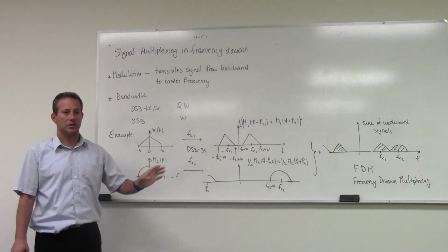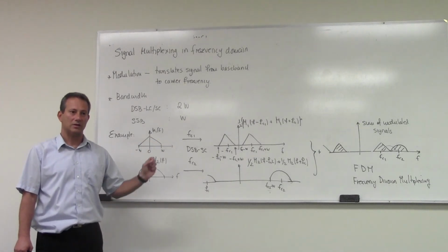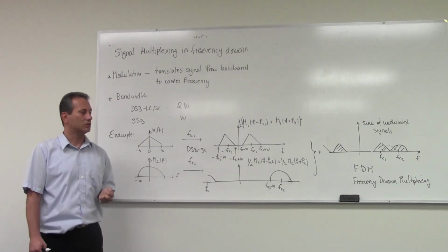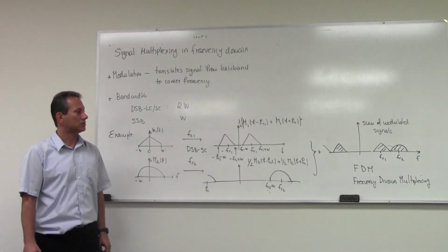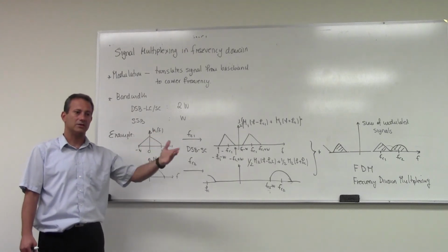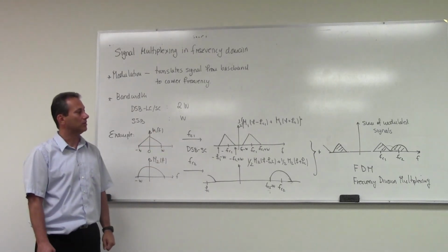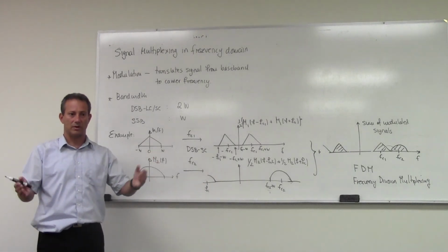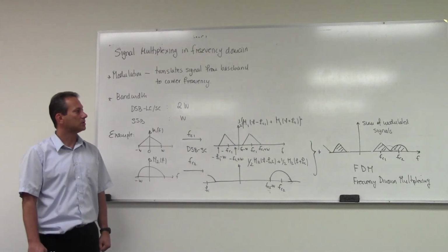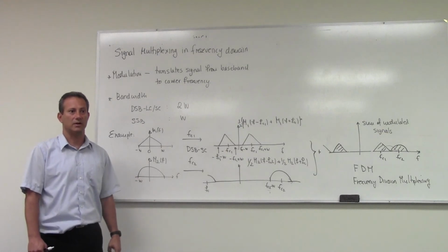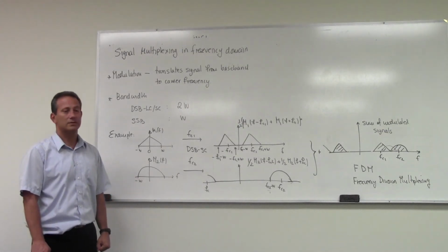Among all of these modulation schemes that you're going to cover, it turns out that single sideband is the most sensitive to the noise. So what that means is your signal-to-noise ratio needs to be very high if you try to demodulate it. And there are all sorts of issues associated with how complex it is and all the linearities that you need to maintain along the way to make it successful. Nevertheless, there are a lot of cases where the bandwidth or the available spectrum is of the highest importance, and anything you do on the signal processing in those cases is justified by how expensive the spectrum is.